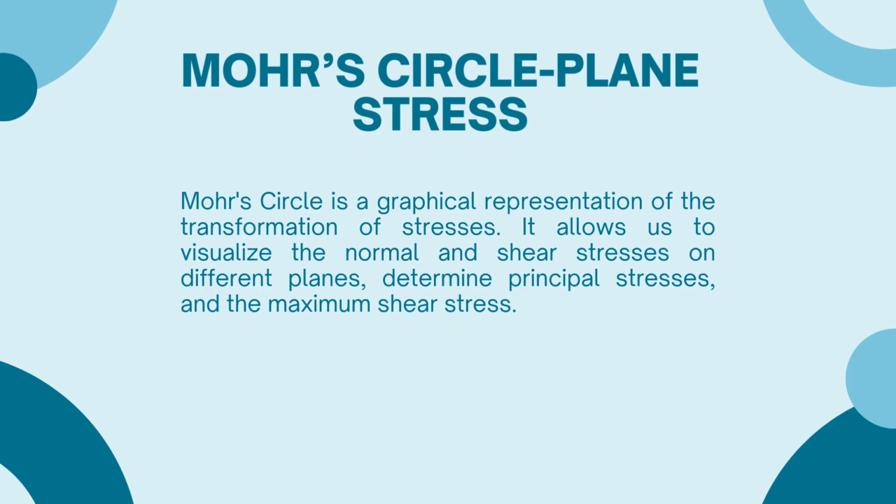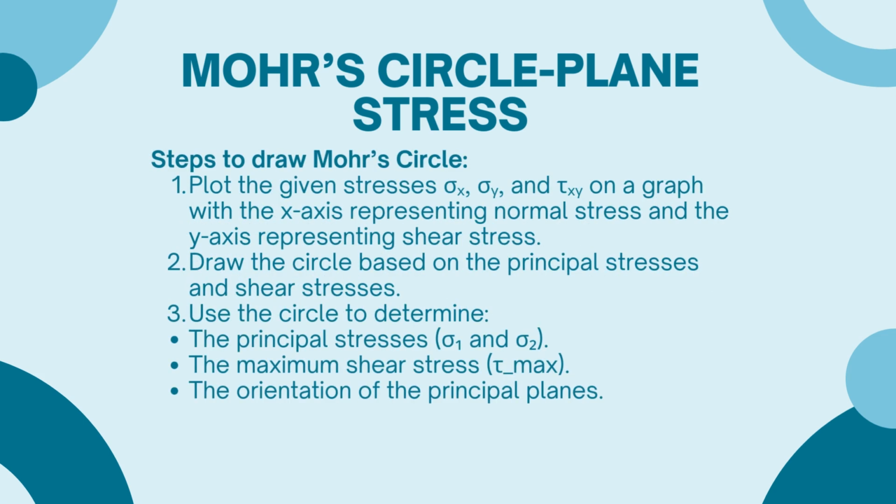Next, we'll discuss Mohr's circle for plane stress. Mohr's circle is a powerful graphical tool that helps visualize the transformation of stresses. It allows us to see how normal and shear stresses change on different planes and helps determine the principal stresses as well as the maximum shear stress. This method is widely used for stress analysis because it offers a clear, intuitive way to understand complex stress states.